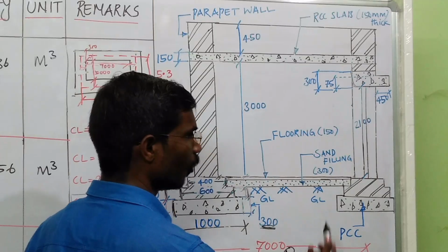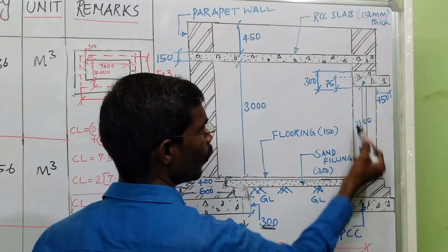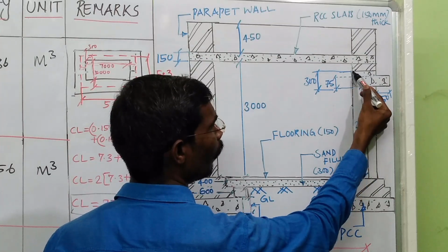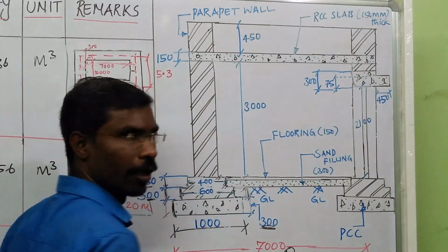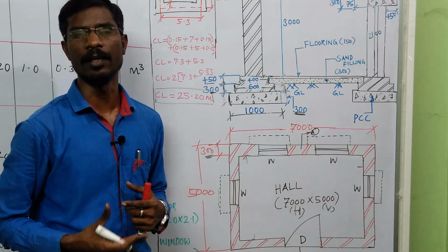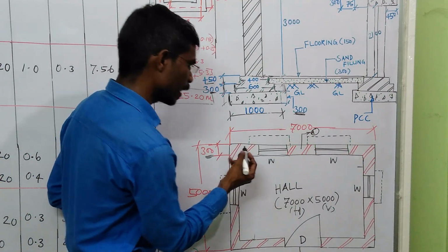Same like that. The wall is from base up to roof bottom. So in this roof bottom, above the opening of your door, we have a lintel. So just deduct the lintel quantity also in this your wall quantity. How we need to deduct the lintel quantity for the doors and windows means, so just take a window.